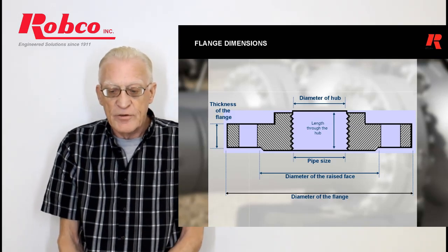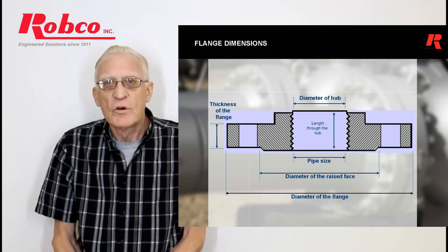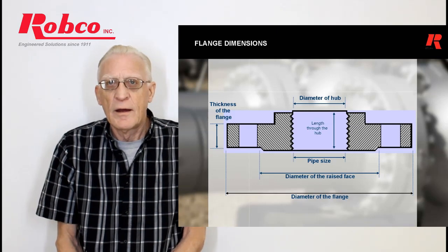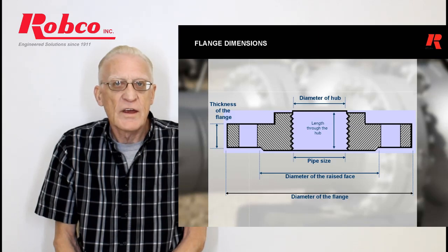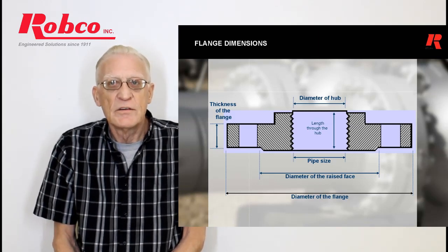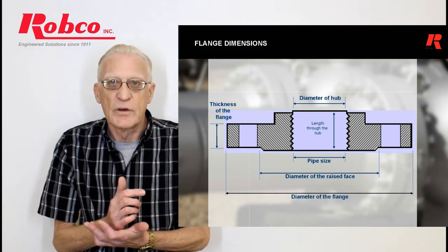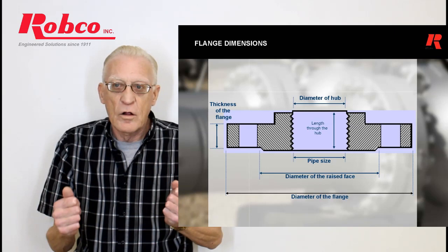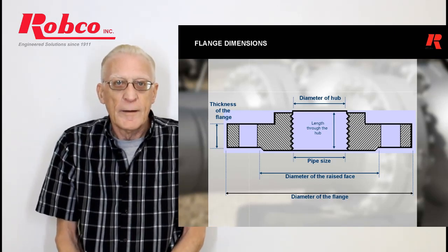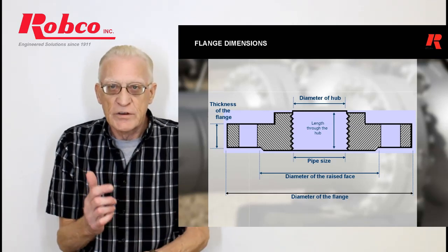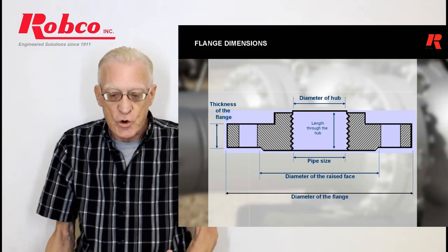So we're looking at a flange at the moment. I just wanted to go back and talk about a flange. What's a full face? What's a ring type? Is flange thickness a problem? Where does the gasket go? A ring type gasket is designed, and I'll make the point right now, that gaskets are scientific. Gaskets are all engineered, they're all specified. You don't have to worry about any swaying. If it's this, it's this. If it's that temperature, it's that temperature, and this is the effect it'll have on the gasketed joint itself.